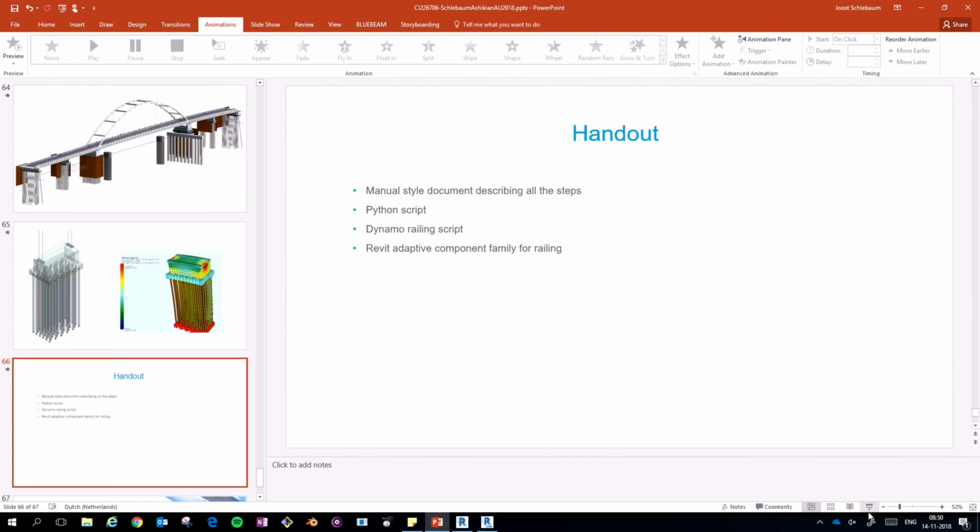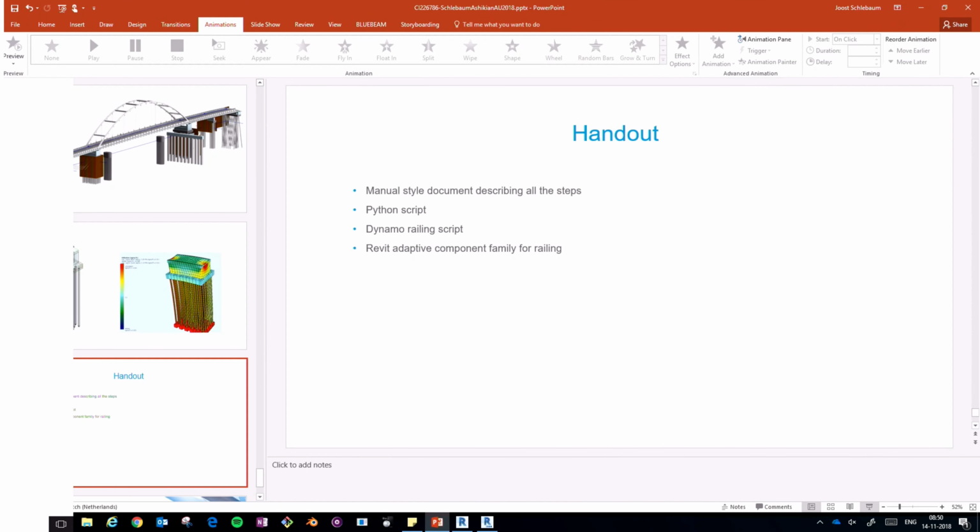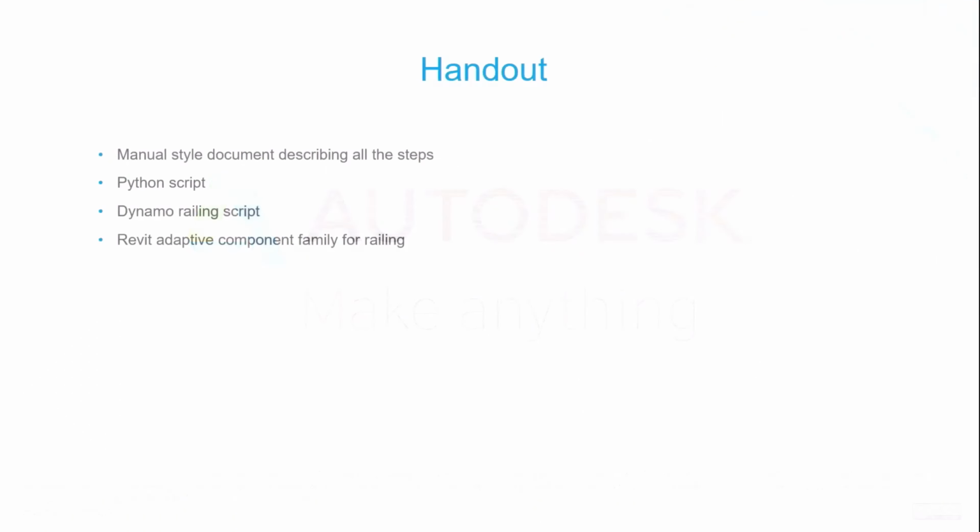Yeah, so that's stage 2. So stage 1, where we added today, you can always go to InfraWorks and make changes, but really you want not only the parameters to be in Revit, but you also want to make at least small changes. All the quantities, volumes will come over to Revit as a shared parameter, but you still want to maybe say, I want to change the diameter of that column. So that's coming as a next step, because Revit by itself cannot resolve that.